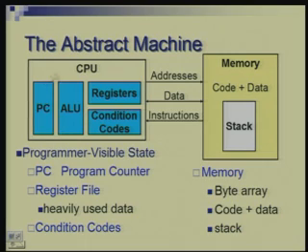The other block or the heart of the whole system is a CPU, where the key components, as I showed earlier, is a program counter and ALU, registers, condition codes. So, whereas ALU is the one which basically performs all arithmetic and logical operations, the operands are contained in registers.